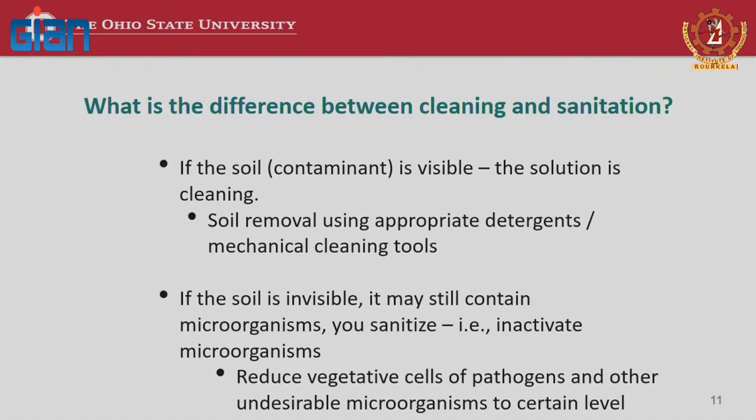So, you have to sanitize. For that you have to kill or inactivate the microorganisms, and you have to do it to a certain level. So, for example, maybe you need about a 3 log reduction, or about a 4 log reduction, depending on the type of agencies you are working with. So, you have to target your sanitation treatment based on those recommendations.